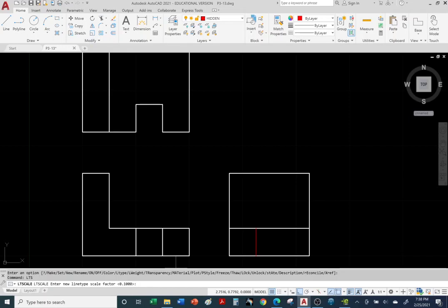Okay, hit enter. So right now my scale is at 0.1. So let me change it to 0.01. I'm just going to move the decimal over. It usually defaults to 1. It should. I just changed it to 0.1 when I sent you these files, at least for this problem. Let me try 0.01. Now keep an eye on the red hidden line.